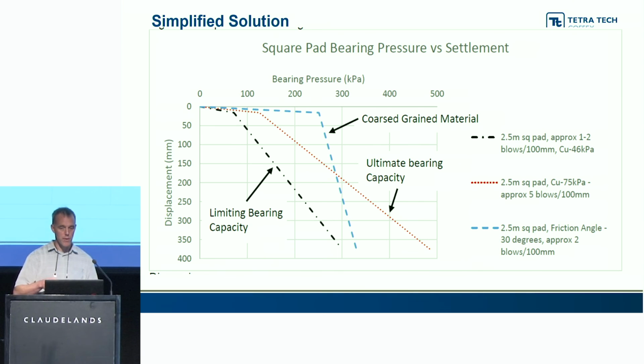on the basis that you're actually testing it correctly to that 5 blows and taking the actual strength of the soils. What we've done artificially, by increasing the DCP count from 3 to 5 and actually reducing the bearing capacity, is we're actually back on this line here. So by introducing that increase in the DCP count, we've reduced our settlement by a factor of roughly 2. It's just for your knowledge.